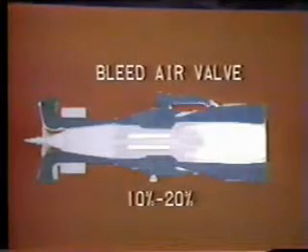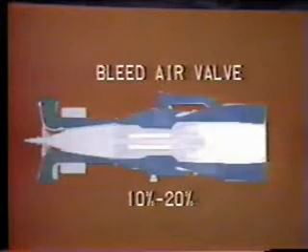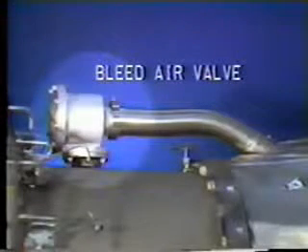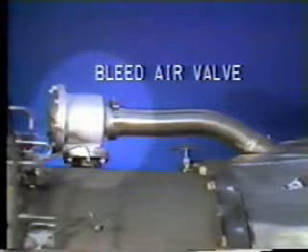Remember, in the compressor, stall was prevented by matching the forward and aft stages during acceleration. The variable guide vane system automatically adjusts for stall. But between the compressor and turbine, another solution must be used. Until the turbine has reached nearly rated speed, the excess air must be removed. This can be done by bypassing the turbine section.